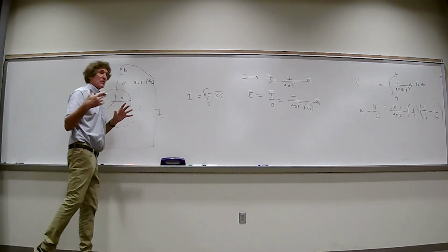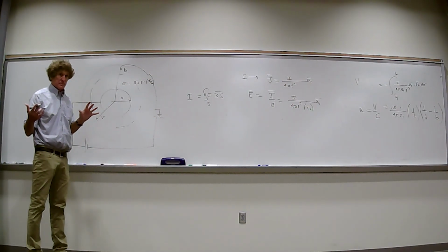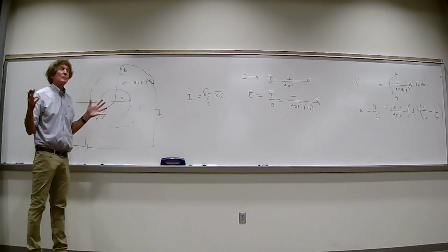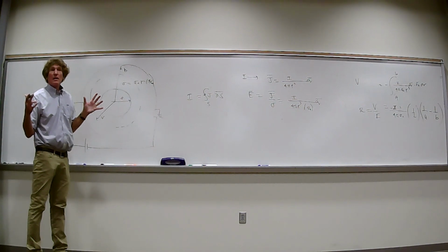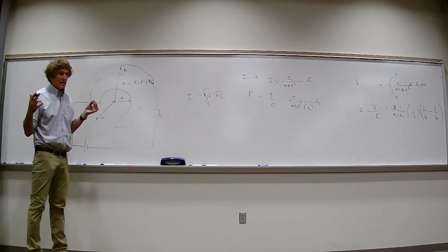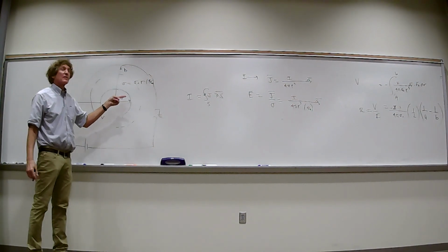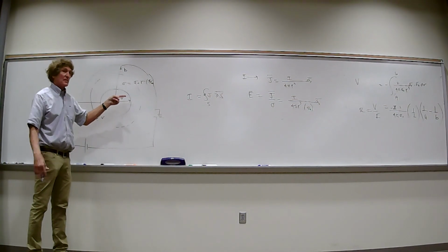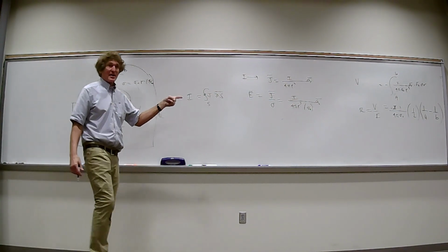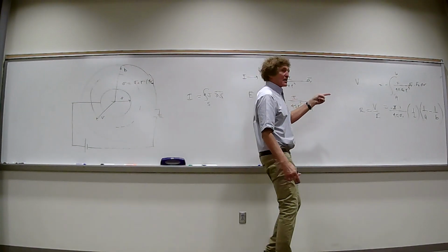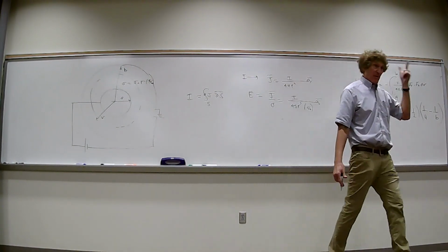How are you thinking about it? So integrate from a to b of what? What are we going to integrate? dr, differential resistance or differential length? Differential radius, okay. What are we going to integrate? That's dr as a differential. What function in front of it? You have 1/σ times 4π r squared. That's E, right? Isn't that right? Yes. We got E from what? From J. We got J from I.